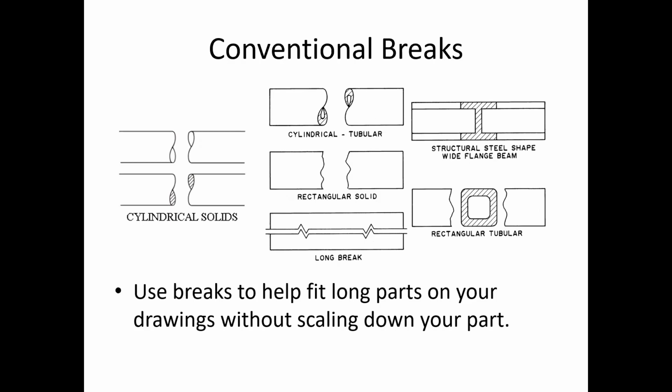Because if a big part has small details, then you're shrinking down. Yeah. I mean, for example, if it was on a D size, that's huge, and then you're scaling that all down so much smaller. It's going to be hard to see everything. Yeah, the consequence of using really scaled down drawing views is crowded and unneat. So the rule of thumb is use full size or bigger if possible. That's especially true since I'm old and I have a hard time seeing stuff.